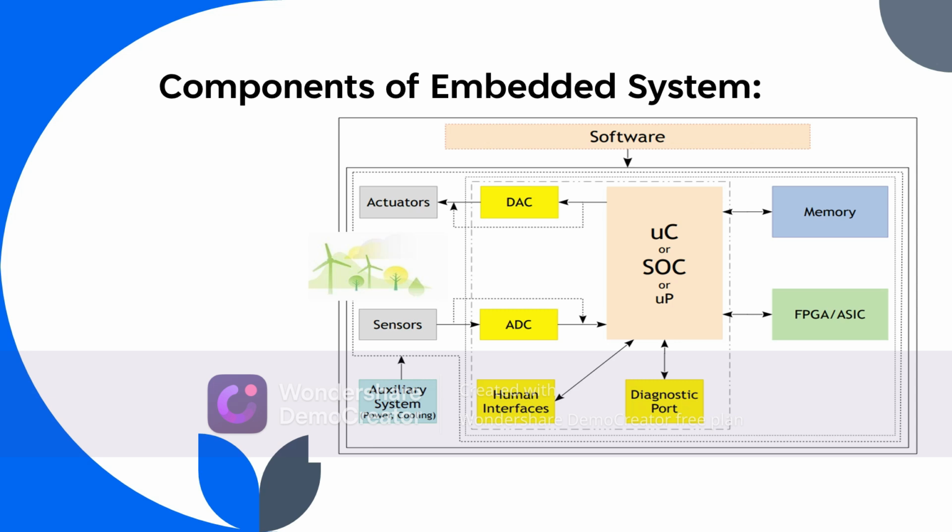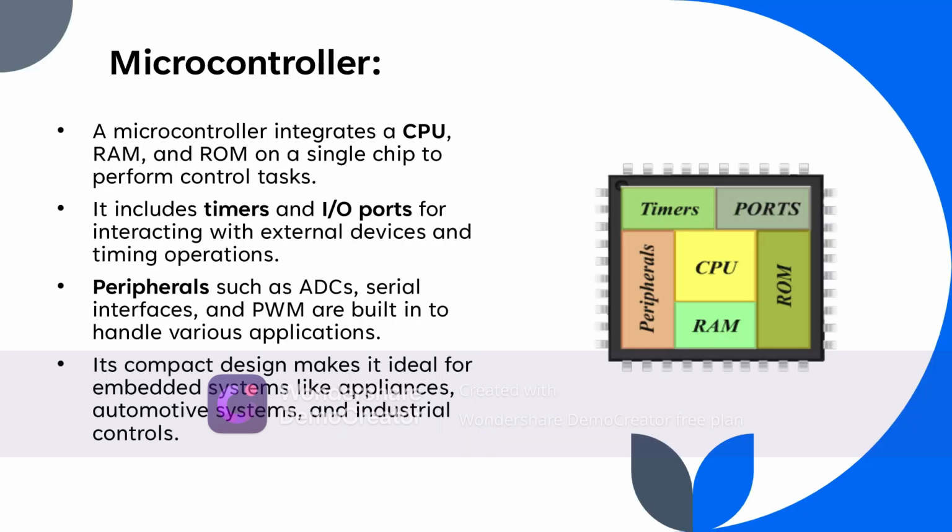It changes that analog to digital form, and then the microcontroller takes this digital data, runs the program, decides what to do, and it is forwarded to the DAC. DAC is a digital to analog converter. Whatever data we are getting from the microcontroller, it converts to analog and passes to the actuators. So this is the process of how any operation is performed by any microcontroller or microprocessor.